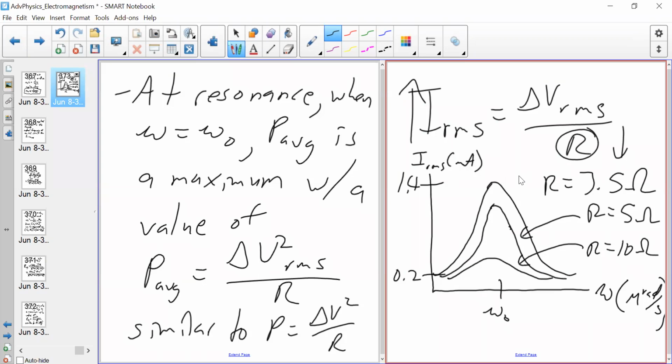So there's something called a quality factor, which is basically a ratio of the resonant frequency and the difference between the resonant frequency and whatever frequency you had. So basically, if you're not at resonance, it's going to be oscillating at some frequency. You just couldn't tune into that particular frequency because there's too much reactance with the inductor and the capacitor, so we can't properly tune into it. So at resonance is what we want.